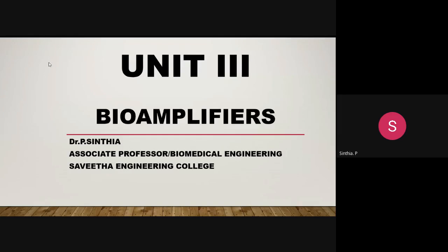Electric, biomagnetic, or whatever signal, they are recorded as potentials, voltages, and electric field strengths generated by different systems, maybe the nervous system, maybe from the heart muscles, or it may be the signal from the eye, right? So all these involve voltages at very low levels. So typically, the range of biosignals will be from 1 microvolt to 100 millivolt.